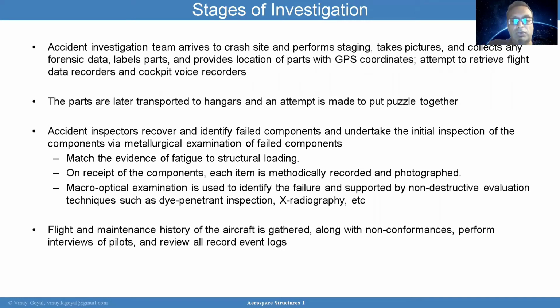Flight and maintenance history of the aircraft is also gathered along with non-conformances, and it will allow you to understand if there's anything in the history that may not have met the quality controls required. Maybe there was an issue earlier in the manufacturing where the thickness was out of spec, and so the non-conformances can help you pinpoint anything that could have gone wrong later. You also want to perform interviews with the pilots. You want to review all the records as well.